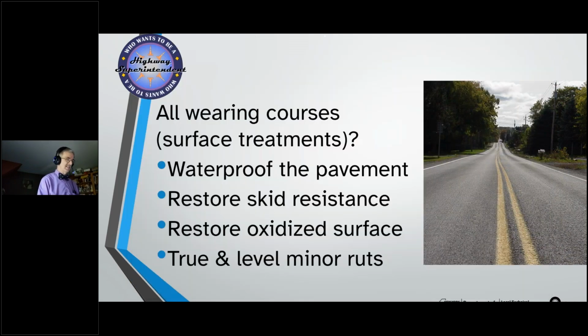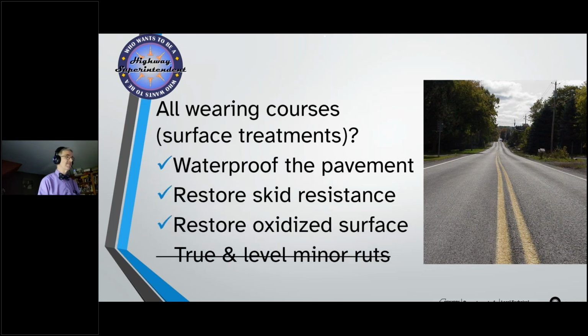I don't know why. But the answer, by the way, is they all waterproof the pavement. That's actually one of their primary purposes, to help keep the water from percolating down through. They all restore the skid resistance, okay? And they all help with the oxidization from the sun. That's their primary purpose, in fact. They're like painting your house, which I need to do on mine. But they don't fill ruts, with some exceptions.